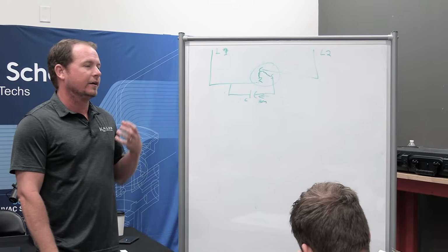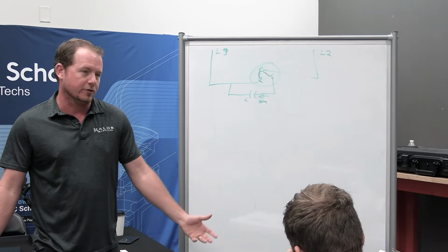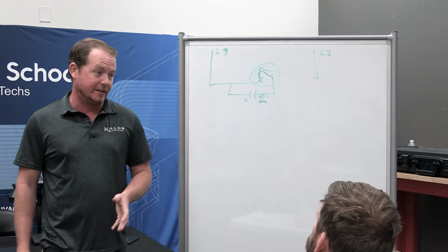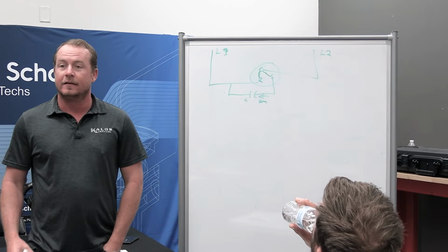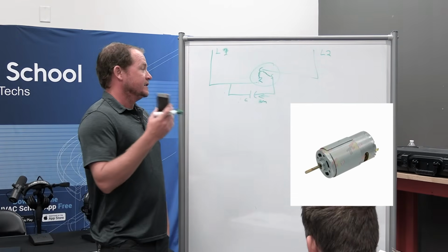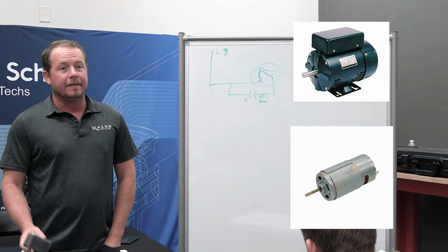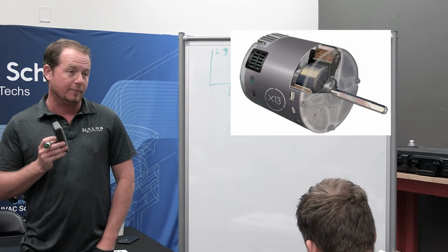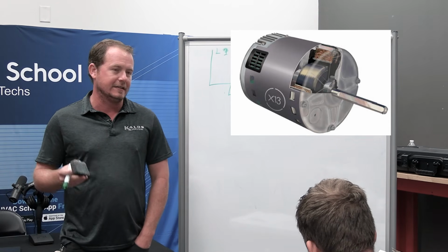Now again, when I put out these videos, the three-phase guys are like, this has nothing to do with us, and that's true. In three-phase, you've got three hands that are spinning it, and you don't need capacitors. That's why you don't see capacitors on three-phase motors. In single-phase, that's where we use capacitors, specifically single-phase PSC or CSCR. In the case of ECM, like Sam talked about a couple weeks ago, we also don't have capacitors. I mean, we do, but not in the same way.